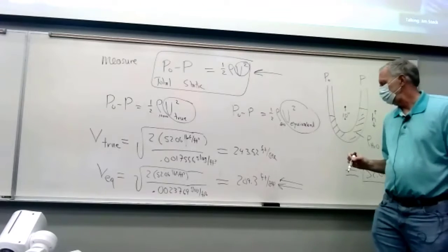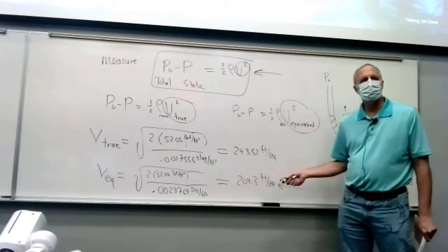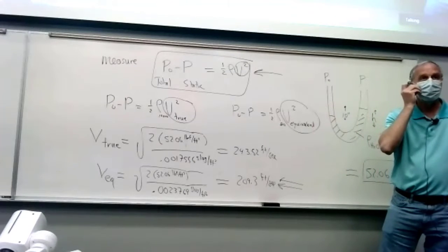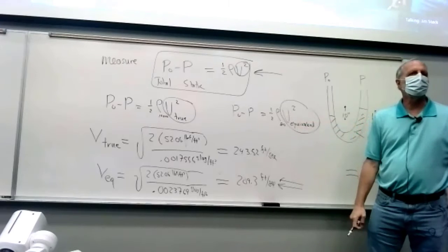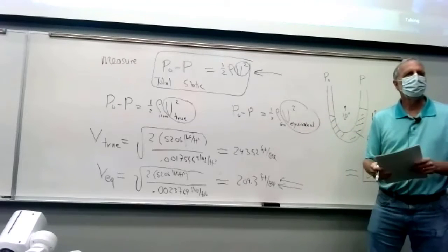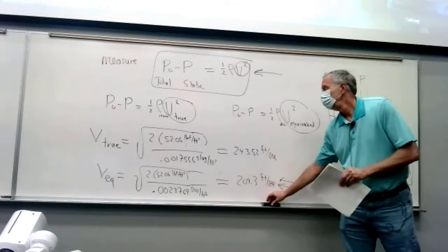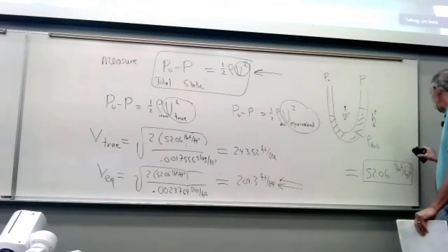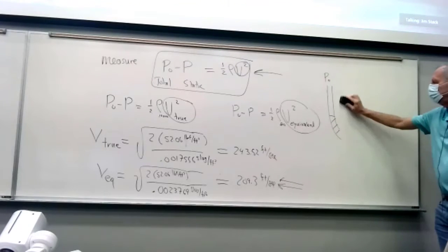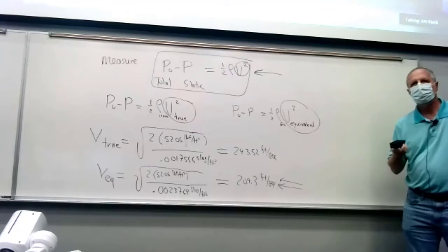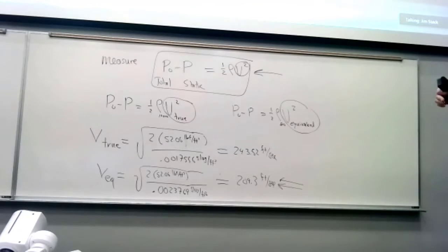And it goes back to the fact that, I'm talking about like a Cessna 172 that uses pitot-static tubes for airspeed. And if you have a computer on board that takes all that information, it will correct for altitude and give you true airspeed or indicated airspeed. Like I said last time, on a car, you can get your speed mechanically from the tires. Of course, if you replace your tires with much larger tires, then the RPM is less per mile driven, and so you'll actually read low on your velocity in your car.